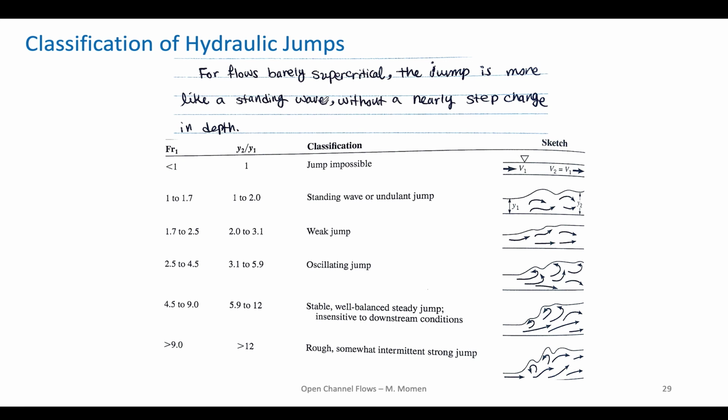For flows that are barely supercritical, that is, the Froude number is greater than 1 but not much greater than 1, the jump is more like a standing wave, without a nearly step change in the depth.